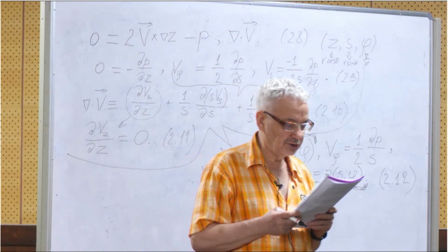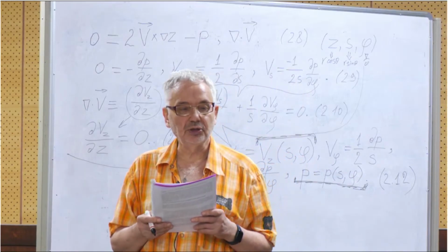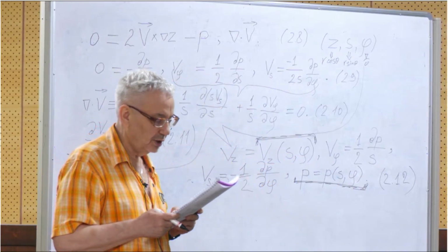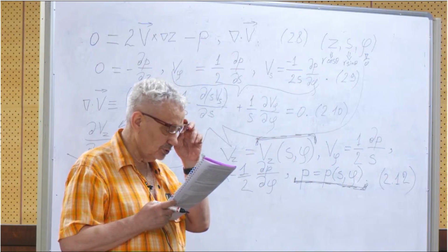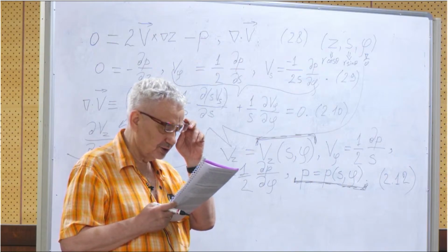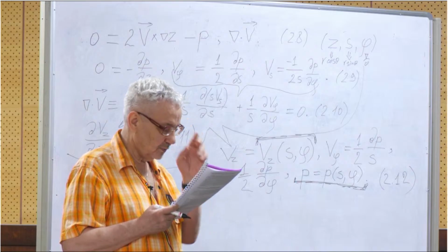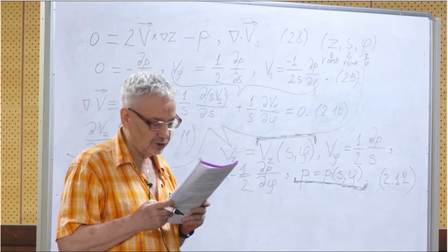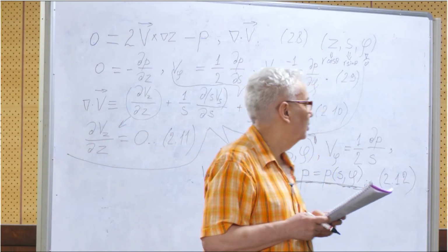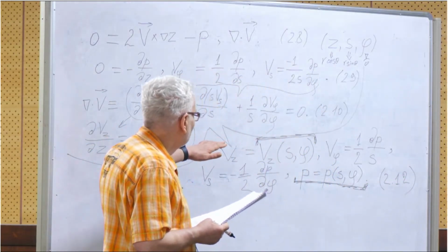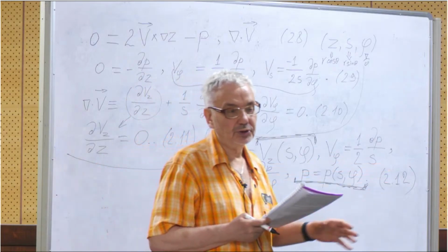This is essentially the Proudman-Taylor theorem. There is even a special Proudman-Taylor theorem, and this theorem proves that the flow does not depend on the coordinate z directed along the axis of rotation when the nonlinear and viscous forces are negligible. There is a theorem, actually. And of course, I show you all the intermediate steps of how to prove this theorem.